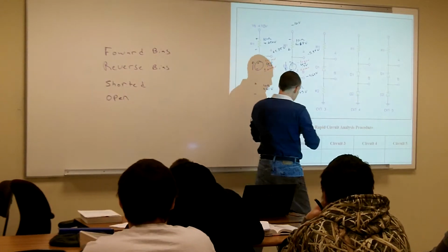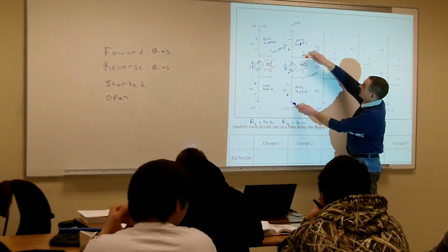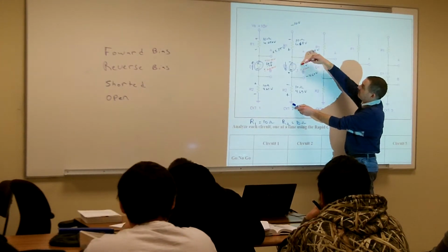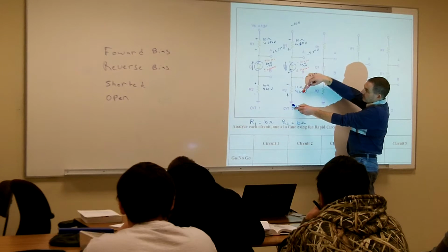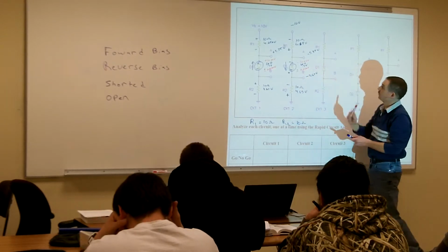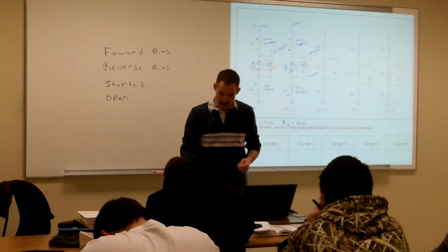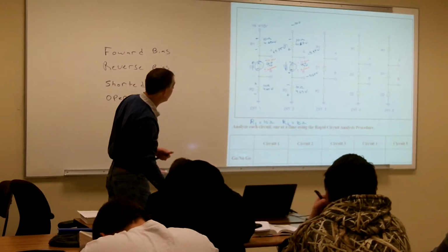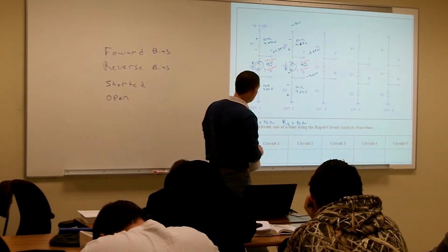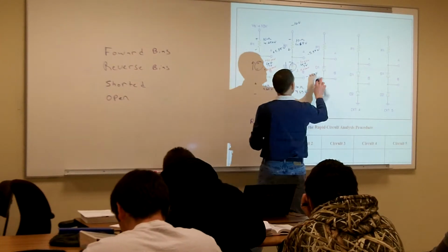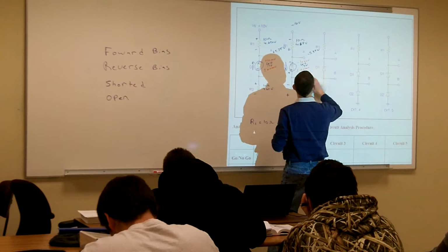So I think so now if we bring our red lead down to our black lead, our first sign is going to be a negative 0.7 plus a negative 4.65. So yeah, it should be a negative 5.35. Yeah, don't forget to throw in your polarities into your resistors, especially on the diode challenge. That one's a little tricky.